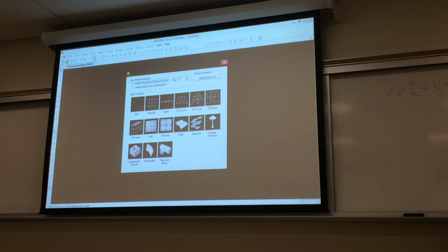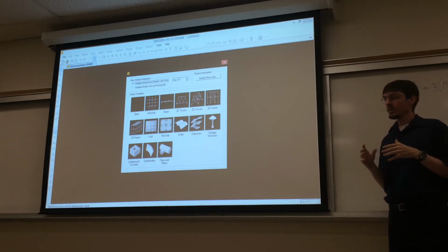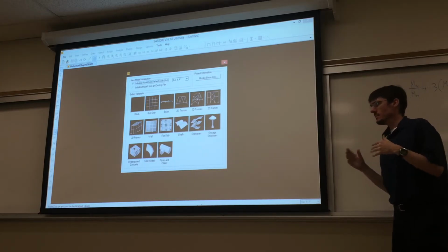So this method has no knowledge of, let's say, CAD drawings, where you're developing the full geometry of a section, and then implicitly just knows everything about that. If you want to use finite element modeling to capture that sort of behavior, say a wide flange beam you want to model in great detail, you can do that by using nodes, but you don't want to think of that process as being synonymous with the analysis we want to do here. We're looking at system level performance of this whole frame. So keep that in mind.